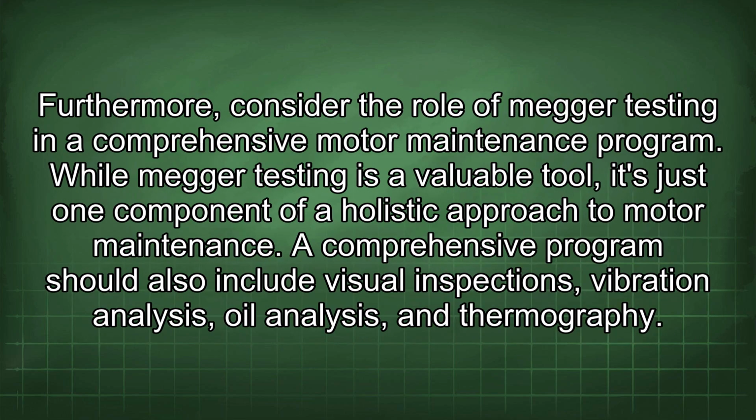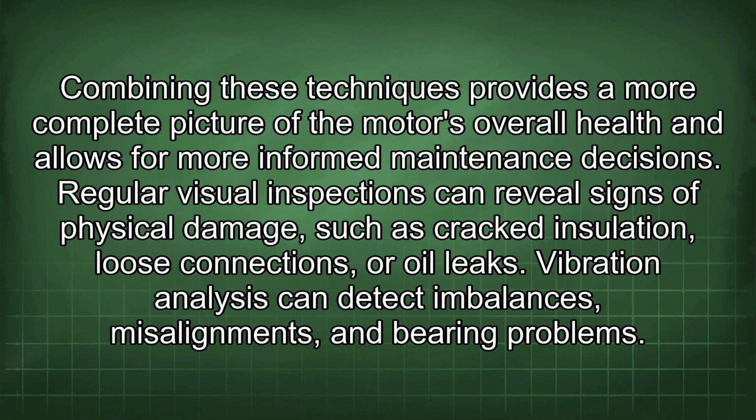Furthermore, consider the role of Megger testing in a comprehensive motor maintenance program. While Megger testing is a valuable tool, it's just one component of a holistic approach to motor maintenance. A comprehensive program should also include visual inspections, vibration analysis, oil analysis, and thermography. Combining these techniques provides a more complete picture of the motor's overall health and allows for more informed maintenance decisions.